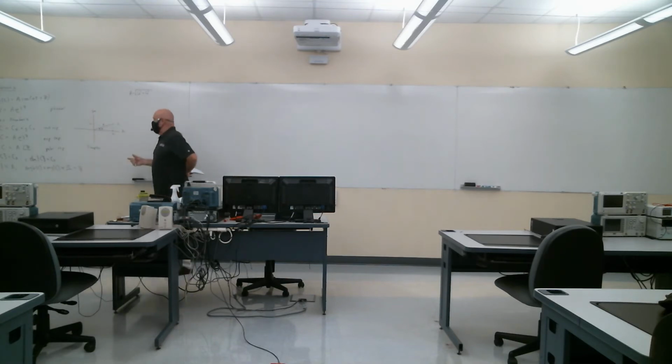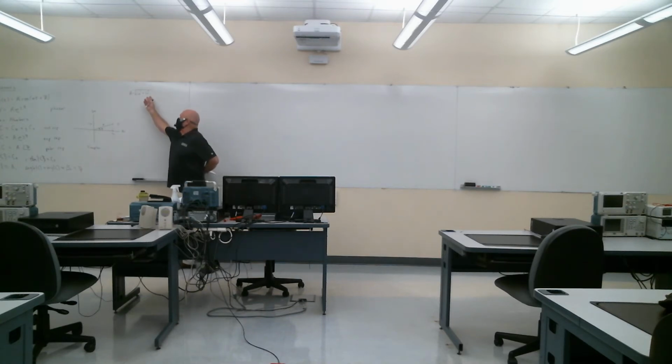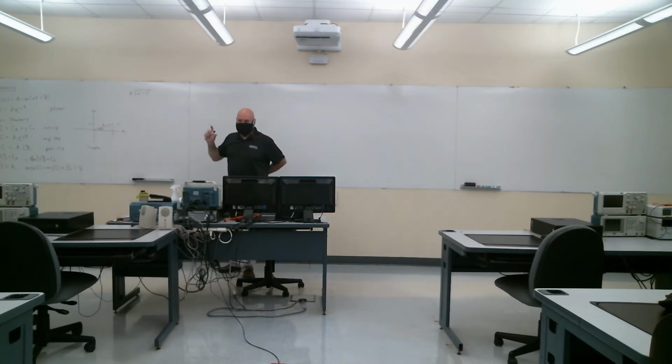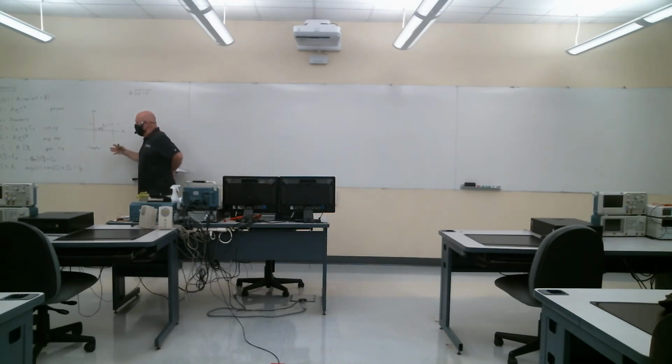Again, this length is CI, it's not JCI. A common mistake students make is for the imaginary part, they put like J3 here. If you square J, you get minus, and that gives you an incorrect result. If it's 4 plus J3, this is 4 squared plus 3 squared, not 4 squared plus J3 squared. C is complex, but CR, CI, A, and Psi are all real numbers.